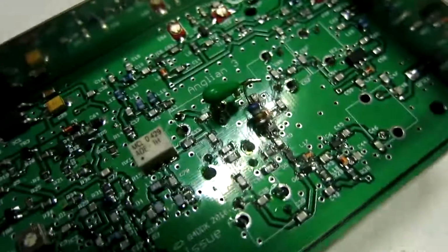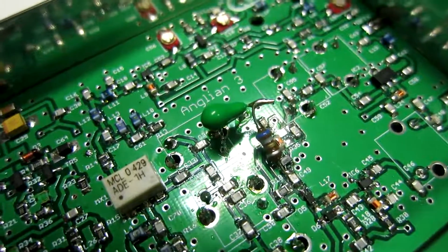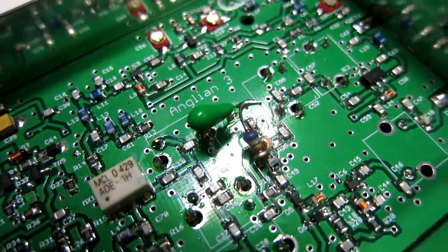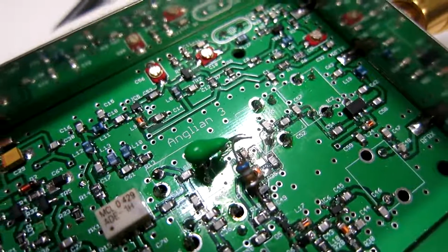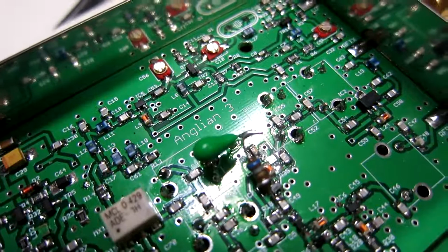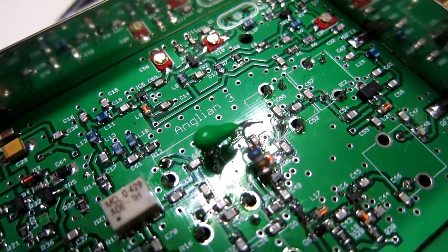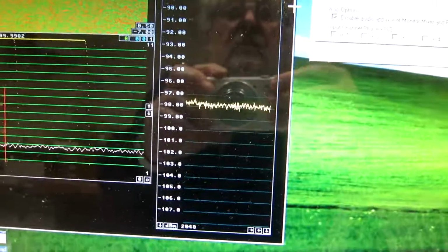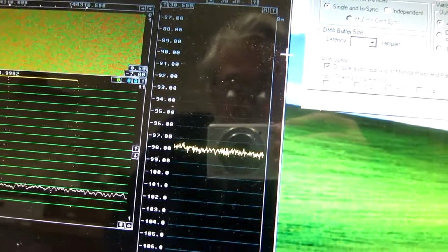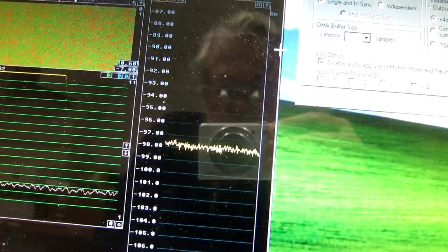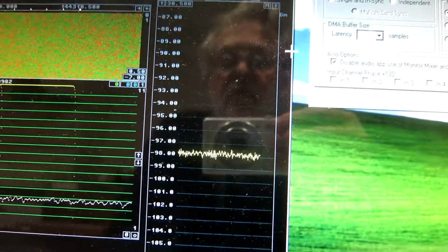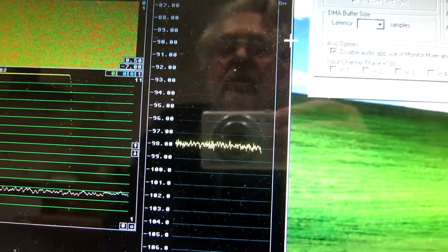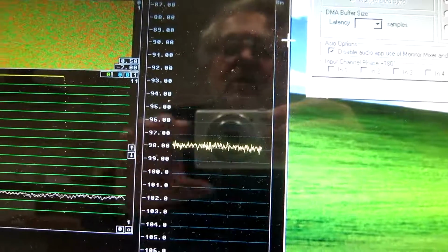So I have tried to put an inductor. It happens to be 6.8 nanohenry, but that's not critical at all, in series with a 10 microfarads tantalum capacitor to make the low frequency noise on the input pin very low. And indeed, this actually made a difference. The noise is now 3.5 dB lower, and not so far away from the minus 102 I was seeing in the receive mode. So there is some more noise source, and I will see if I can find it.